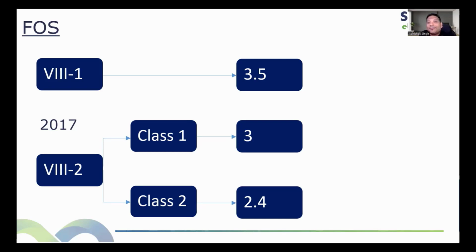Now, if the class is 2, can I overrule the design by rule Part 4 and use Part 5 for Class 2? Can I overrule the thickness calculation by Part 4 and use FEA to design the component?